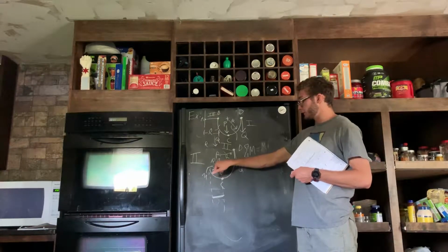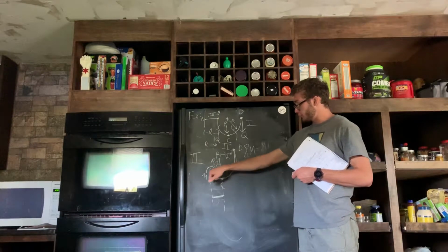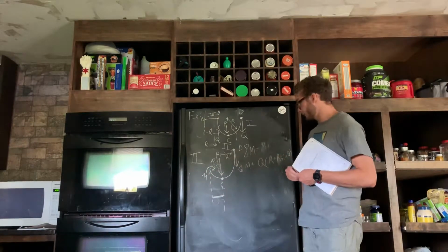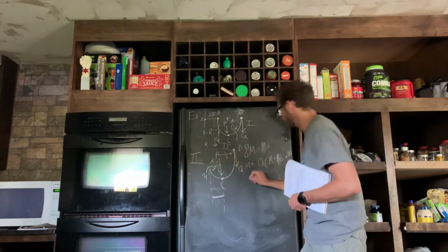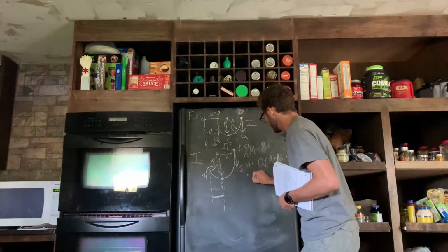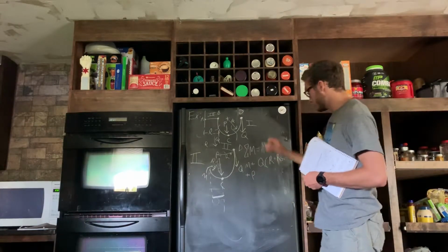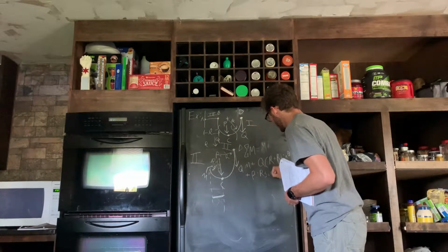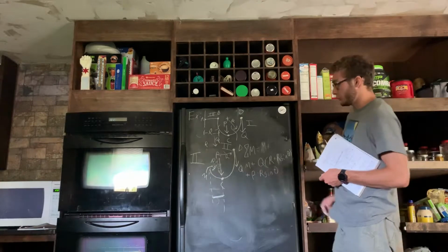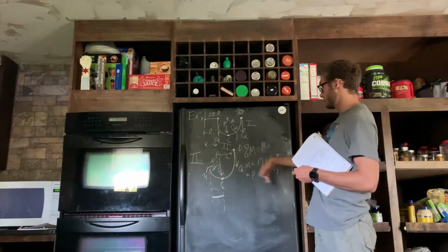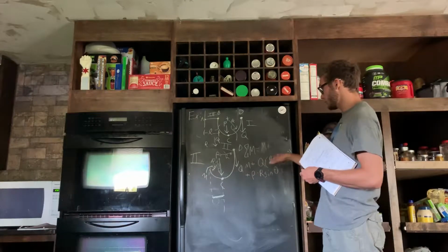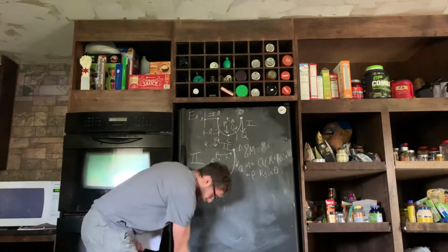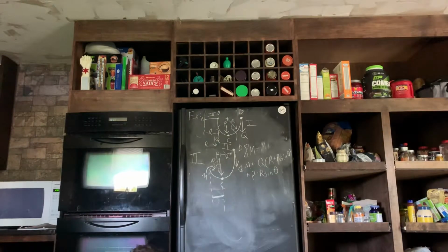You can see that since this is the angle theta, our x value would be the far end away from theta, which would be the sine of theta, and this initial R. But now we also have the P force, which once again will be positive in this case, so plus P, and that will just be P times R sine theta. Pretty simple there. Then when we solve for the moment, it'd be negative. Both these become M equals negative Q times (R plus R sine theta) minus P times R sine theta. So once again, I'm going to write that down here to remember it for later.